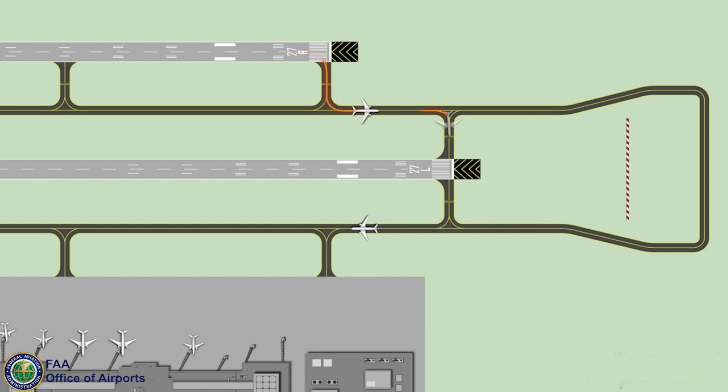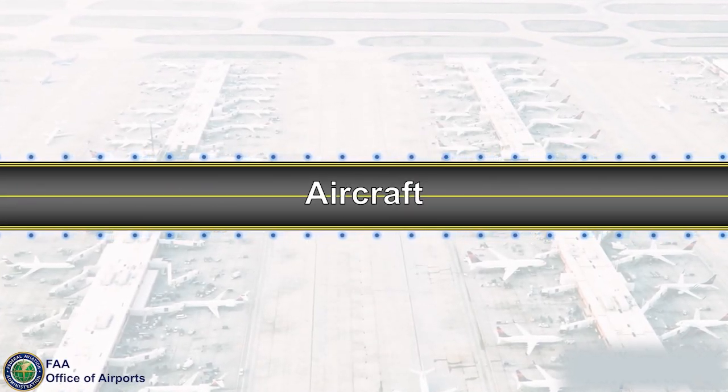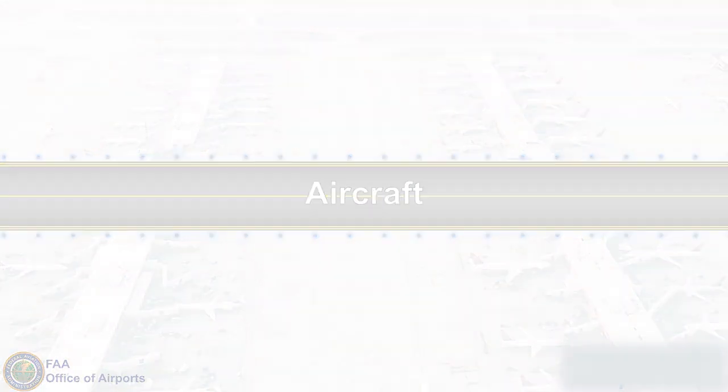It is recommended practice to construct the EAT below the runway end elevation. This minimizes the necessary distance between the end of the runway and points along that portion of the EAT crossing the extended runway centerline. The aircraft types are important EAT design factors.